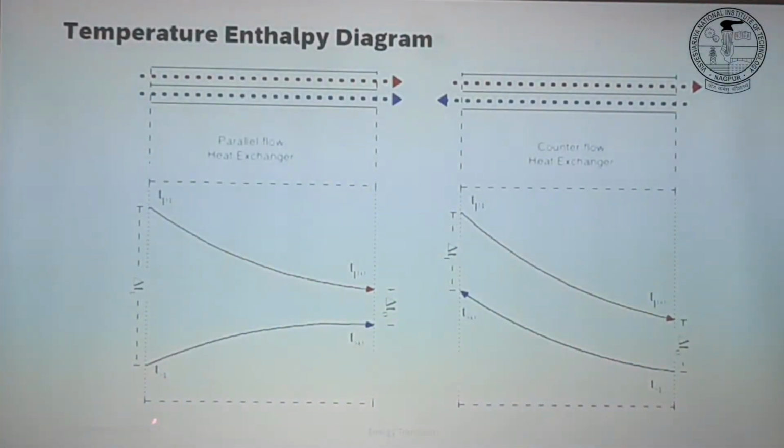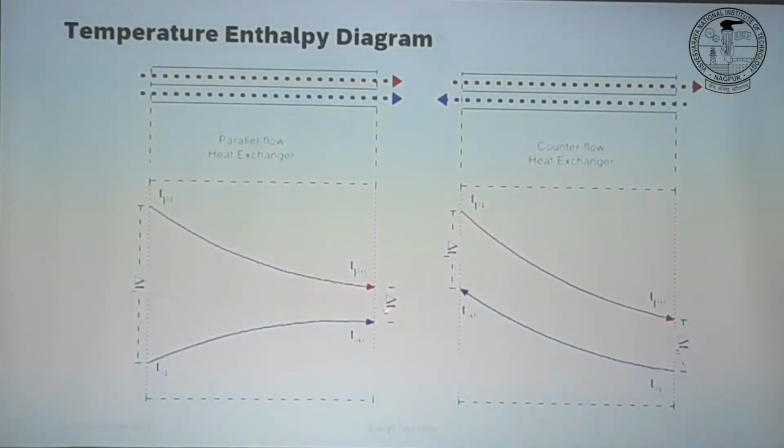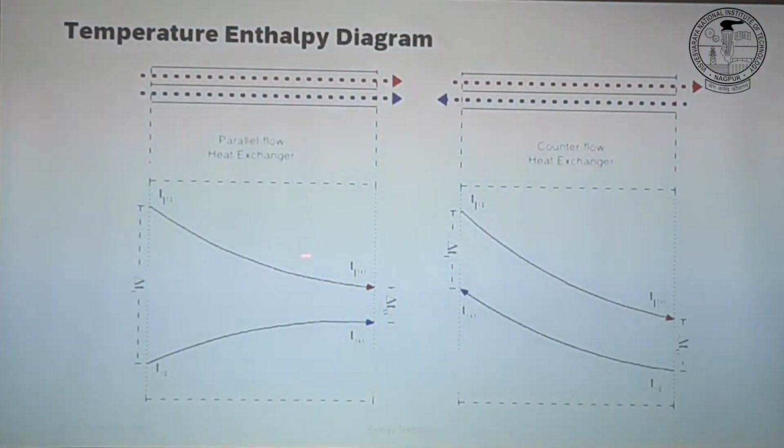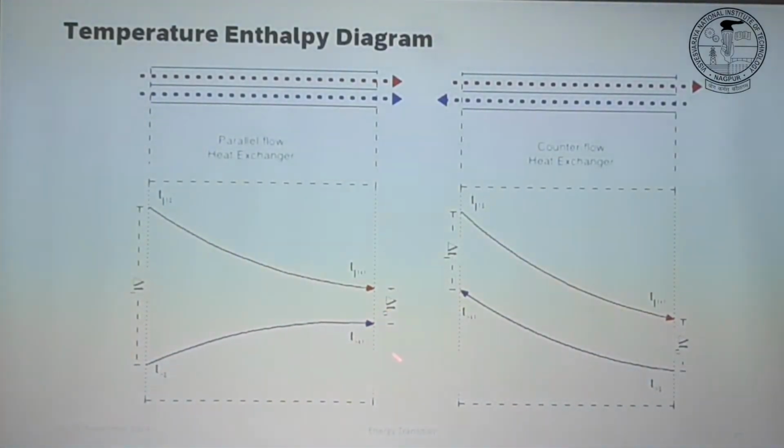So if I draw two pass, that's the side where the cold fluid is entering. On this side it's returning, going here and exiting somewhere here, right? So you could see here you can have a cross. So that's the counter current. So one pass is co-current, another one is counter current. Means we have to increase the number of passes.